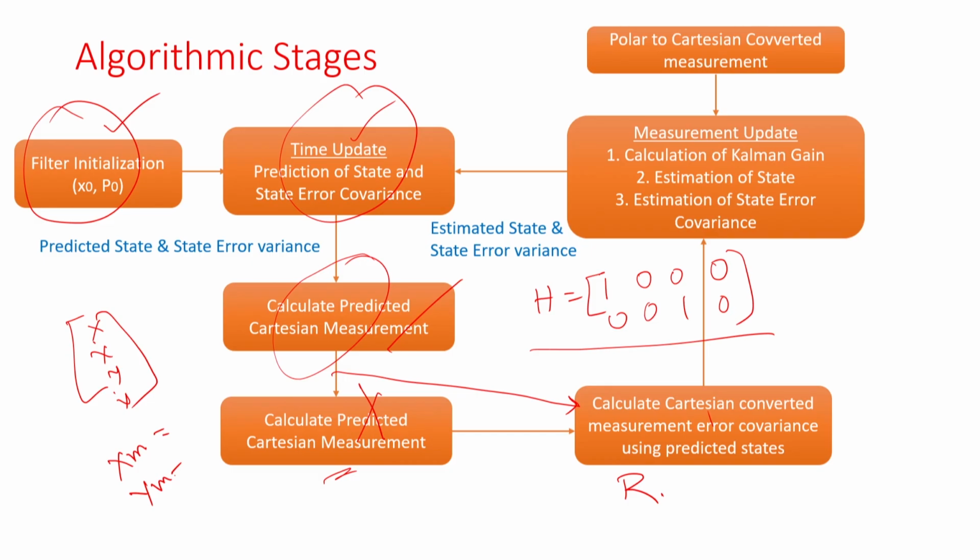Same thing can be extended for 3-dimension also for radar. Here it will be r, theta, phi. So, range, azimuth, elevation, your elevation is also there. You can simply bring it from polar to Cartesian. With this you can now run this pseudo measurement filtering approach.